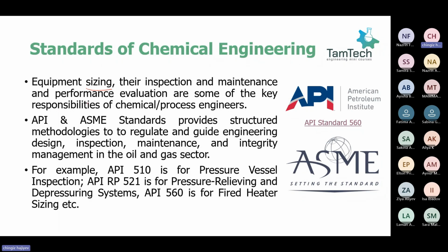Some of the famous API standards that, as Talia mentioned, we should know as process engineers are API 510, which is for pressure vessel inspection. RP stands for recommended practice. API 521 is for pressure relieving and depressurizing systems.